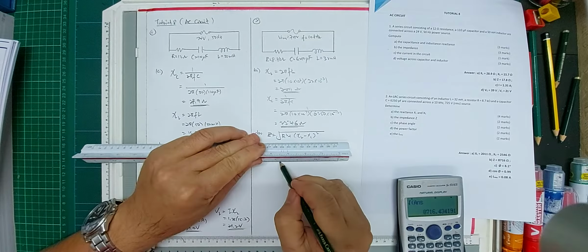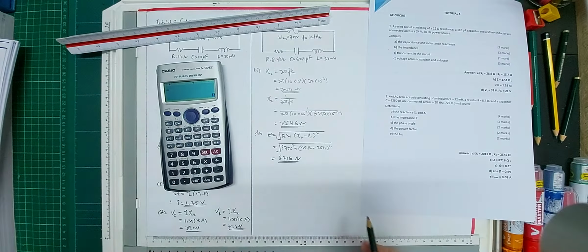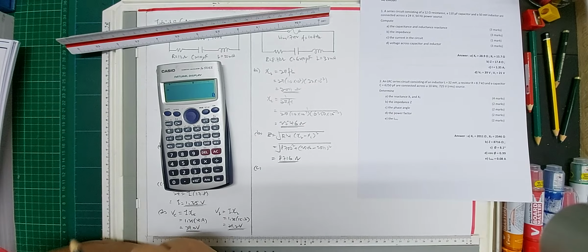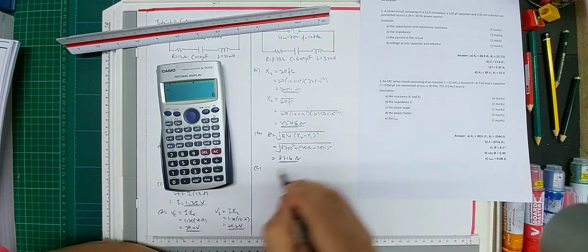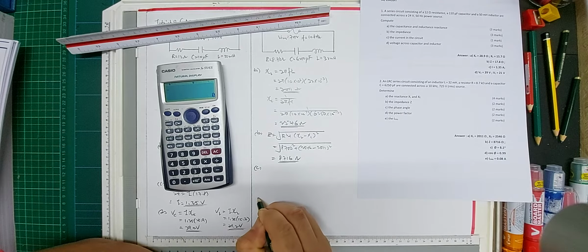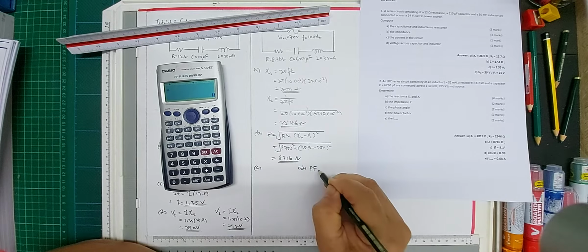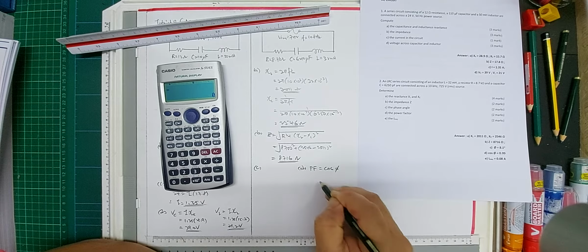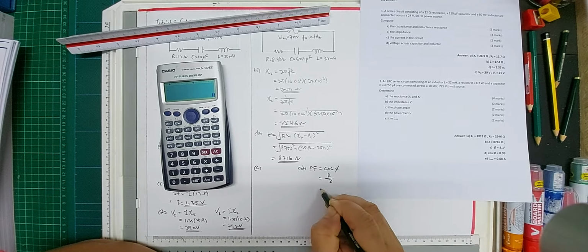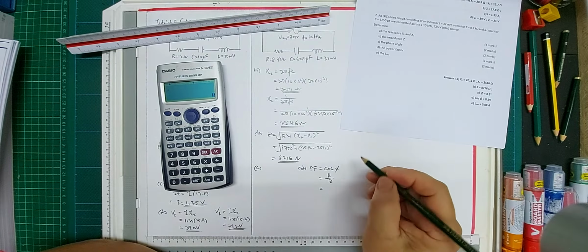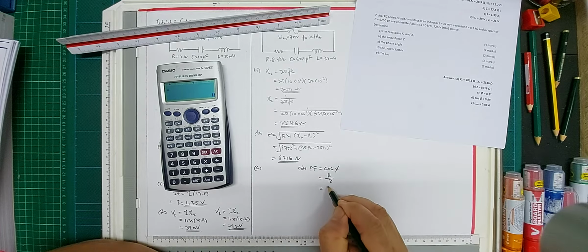That is a total, total resistance and reactance in an AC circuit. C, the phase angle. Okay, what is phase angle? Phase angle is related to the power factor. I'll do power factor first. So power factor, PF, is actually equal to cosine phi, and this value is R over Z. So you have this power factor formula, your R is 8700 divided by